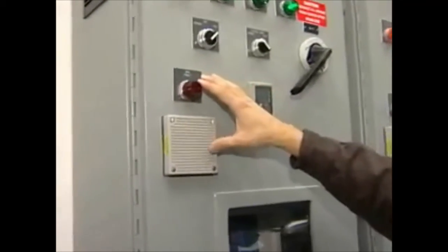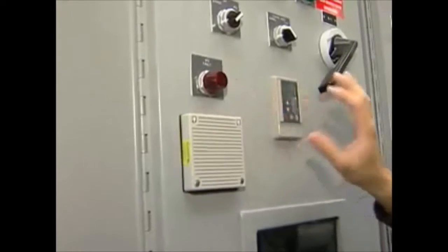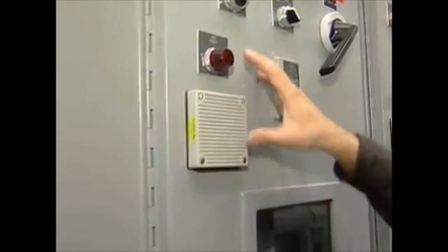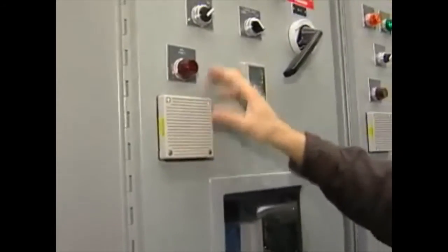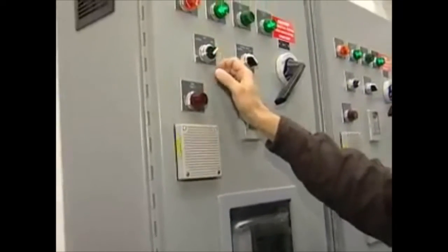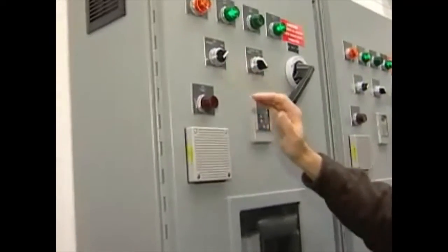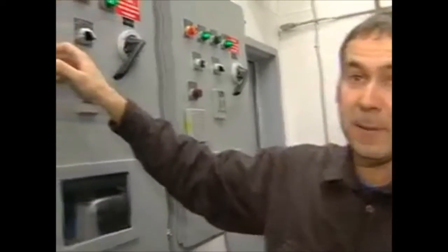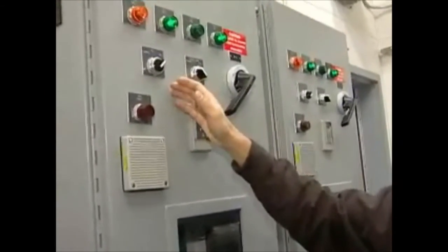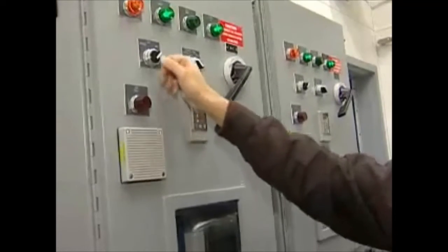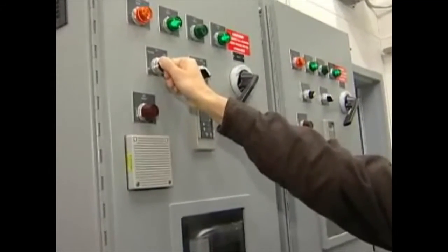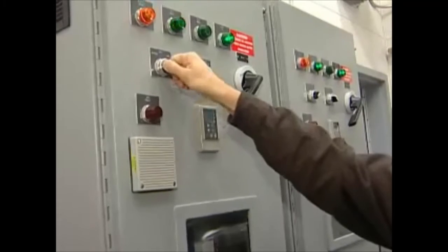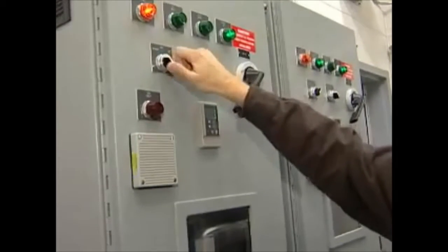We have a VFD fault. In the event that the VFD device itself fails and we get an alarm and it quits working, we have a bypass mode. In the bypass mode, it turns the fan to full speed and it just runs continuous. So if you had a failure of the control device for some reason and you were overheating, then you could turn it into bypass mode on a temporary basis, and that would run and provide cooling. So I'll demonstrate how that works. When we go to the bypass mode, we'll hear the fan ramp up to full speed.